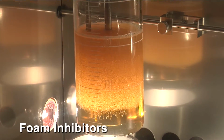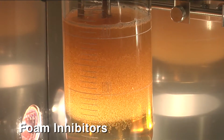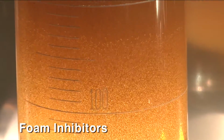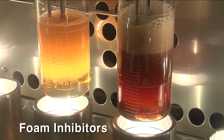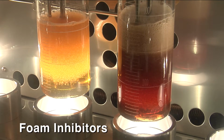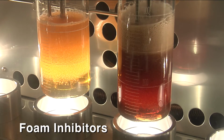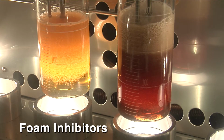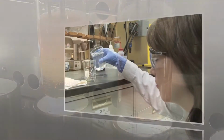The final additive is the foam inhibitor. As gears rotate quickly through oil, they can cause foaming. That results in power loss and reduced axle performance. It also breaks up the lubrication layer, leaving metal surfaces unprotected. Foam inhibitors change the surface tension of the foam bubbles so that they break up more quickly.